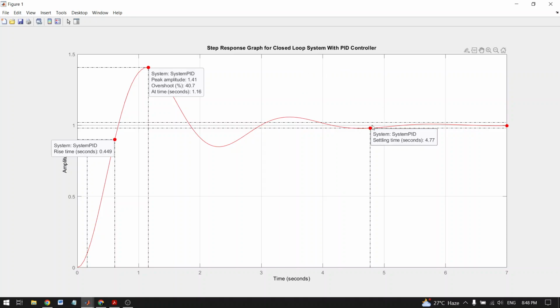In the PI controller, it took much longer for the system to reach the steady state, but here we add the D controller into the PI controller, because the derivative controller has the effect of making the system much more stable and decreasing the settling time. And here we get the steady state equal to 1.